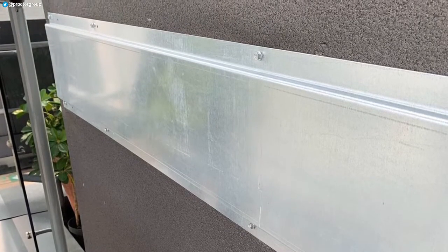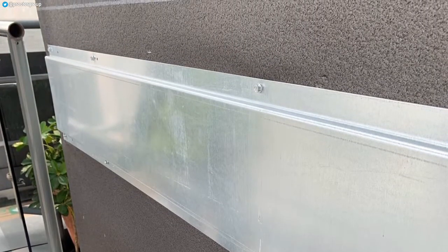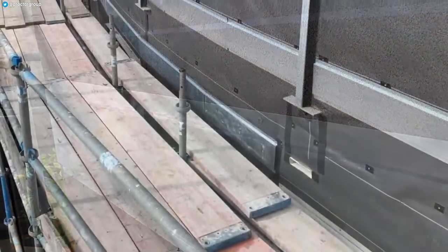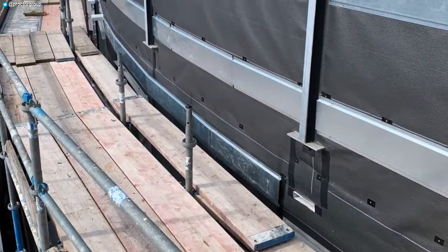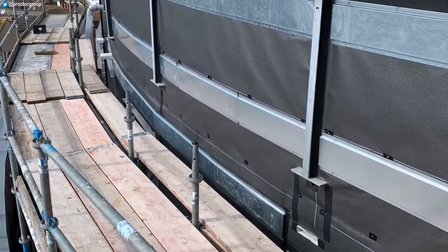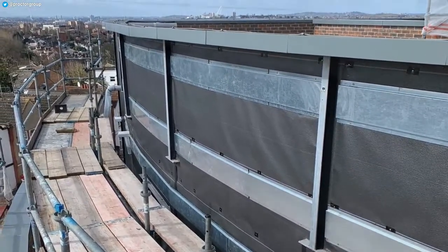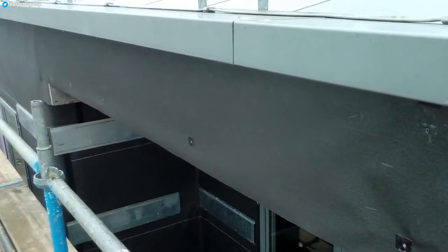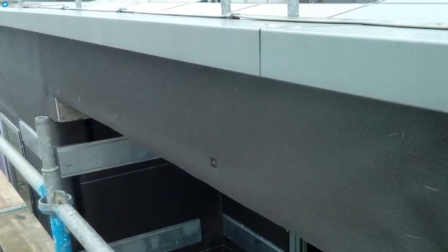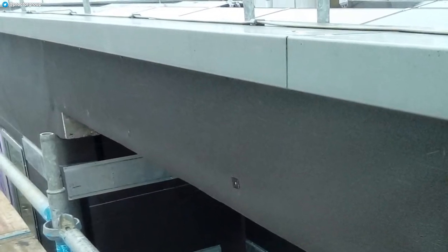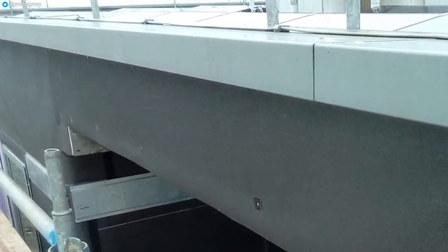As part of these works, the vapour-permeable fire shield membrane was specified to provide additional protection not only from weather but also from fire spread within the cladding system. As part of a project specifically focused on reducing the combustibility of the entire facade construction, the intumescent surface of the fire shield membrane made it the obvious choice of membrane to provide temporary weather protection without compromising the overall